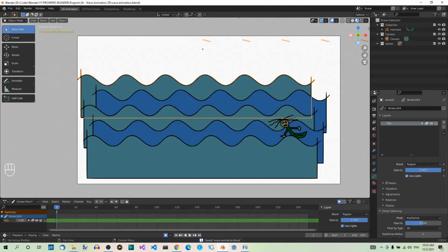Step 22. Start a wave animation. Now we want the waves to be animated. They will just slide from left to right and back. We're gonna animate particular rows of waves. Make sure you're in object mode. Now our animation is gonna last 10 seconds, which means we need 240 frames. It's gonna be played at 24 frames per second.